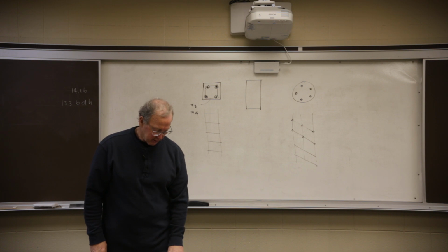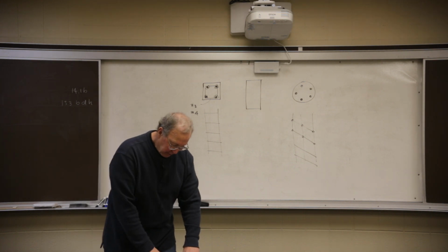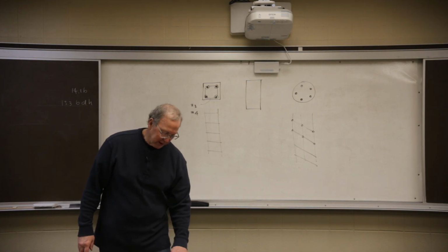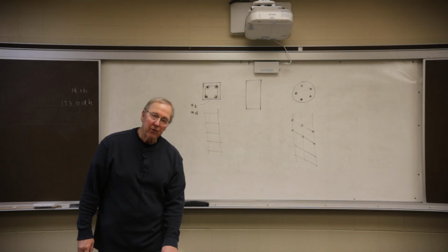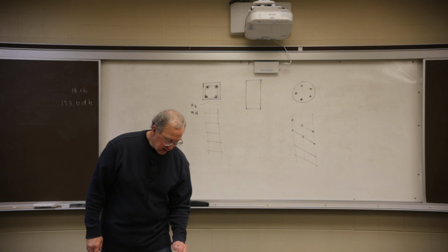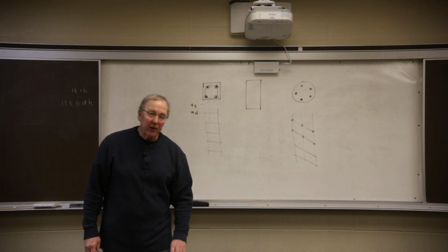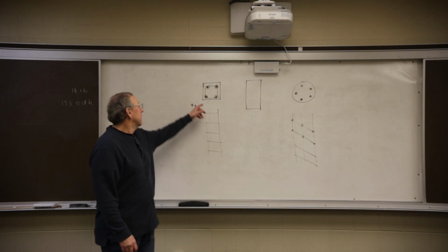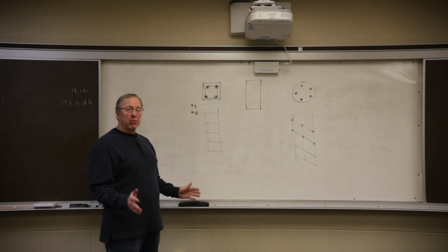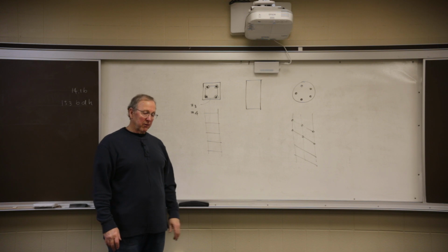Okay, this is general information basically, to give you an idea. The chapter isn't centered around that. It's centered around tables. If you go to page 501, you see a bunch of layouts. It shows you what could be and what you could see on drawings when you get in the field. Okay, then you go back and it shows you about forms. Hopefully you know that we make this out of plywood. We make a form out of plywood and then sand it up and plumb it and then drop the cage in and then we fill it with concrete.